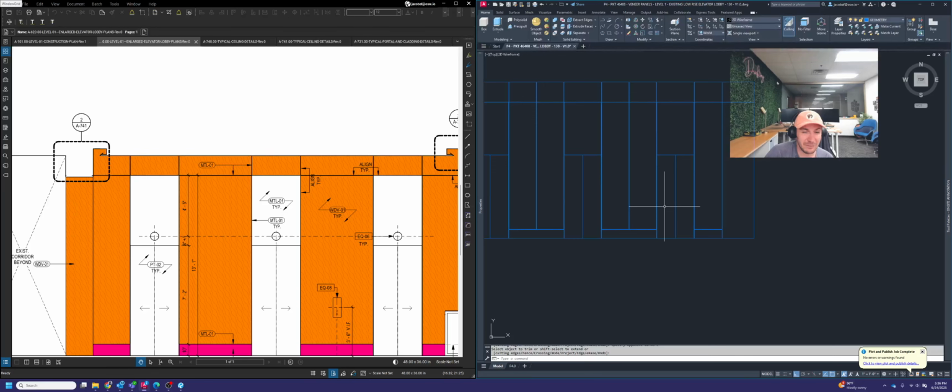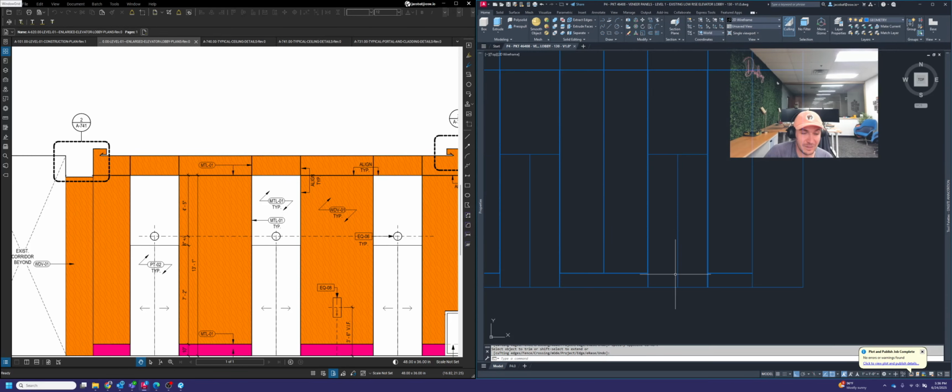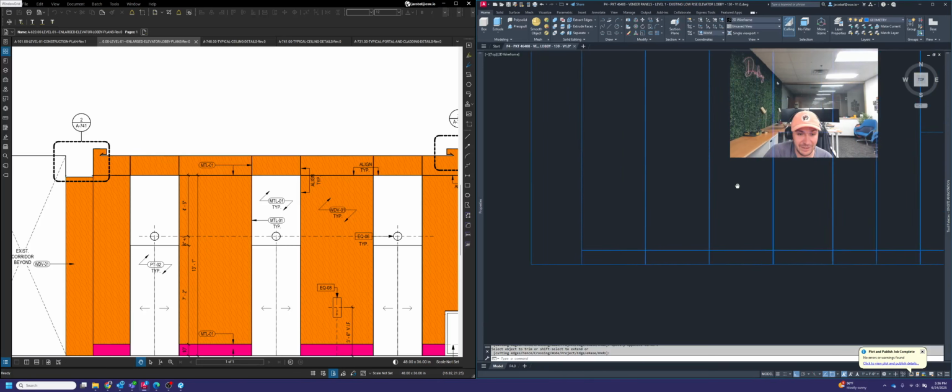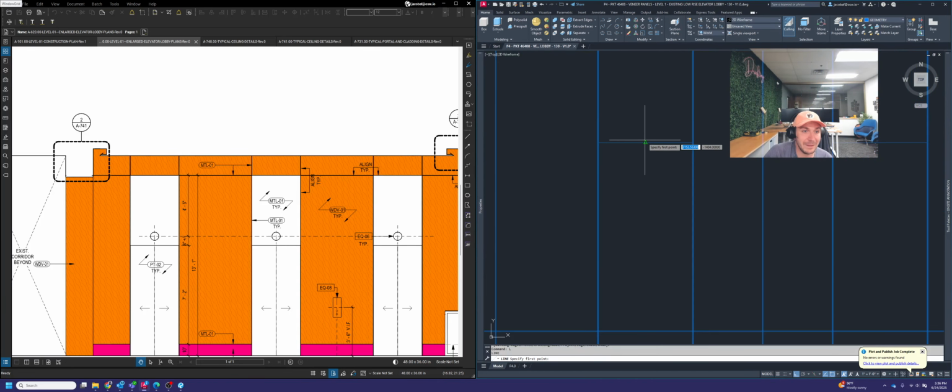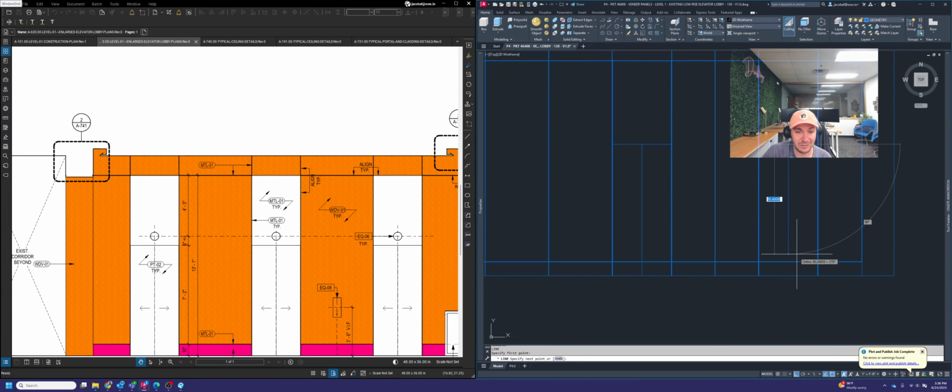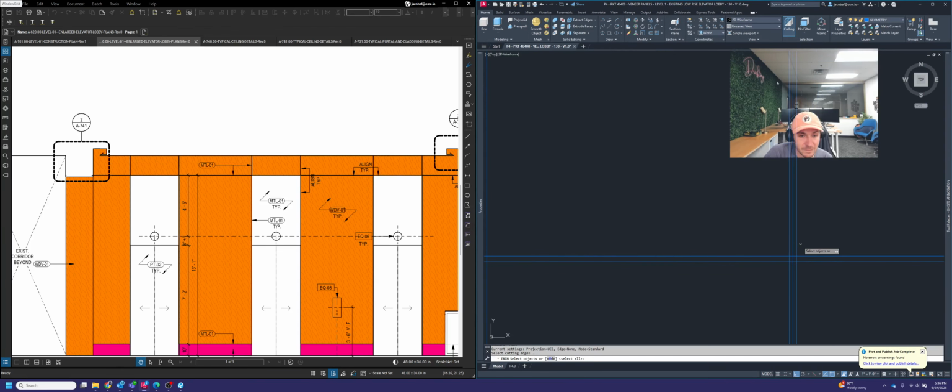The only thing that we don't have right now is I didn't include this line in the middle of the doors, so we need to add that as well. Oh, and trim out the base trim that's sitting inside of the elevator doors right now because that wouldn't be there. So let's trim that back to where the elevator opening would be, there and there.